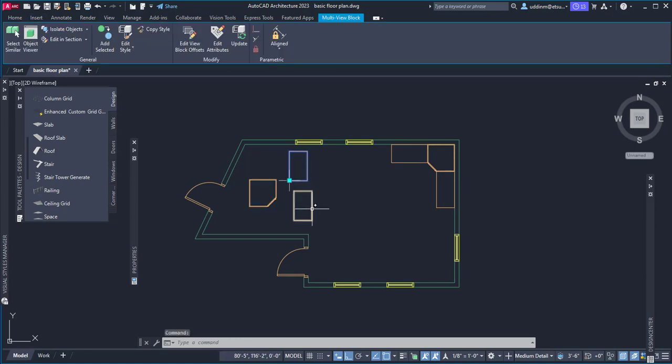When I select this cabinet here and that little box shows up, this box is showing up on the back of the cabinet. So this is the front. When you're looking at the cabinets in 2D like we are now, sometimes it's hard to distinguish the front and the back. So if the front is needed over here on this side, you need to rotate this as well. I just want to make sure that you know that. Same thing applies here. If you select this, this is the back of the cabinet. If you select this one, this is the back corner of the cabinet, therefore making this the front.